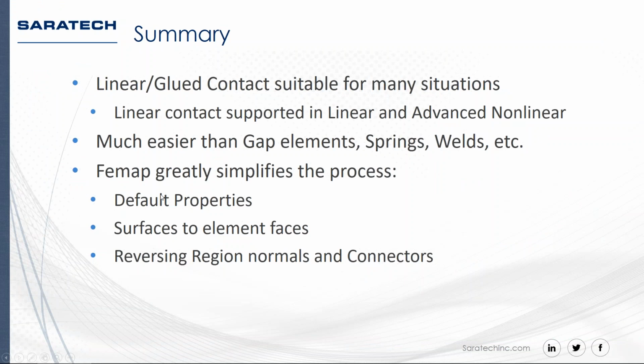So to wrap up, linear or glued contact is suitable for many situations, but you do want to keep in mind if the model may need to go into a nonlinear solution. Also remember, linear contact is supported in the linear solutions like static, modal, and in the multi-step and advanced nonlinear solutions, but not the basic nonlinear. This is all much easier than doing gap elements, springs, welds, and other things like that.